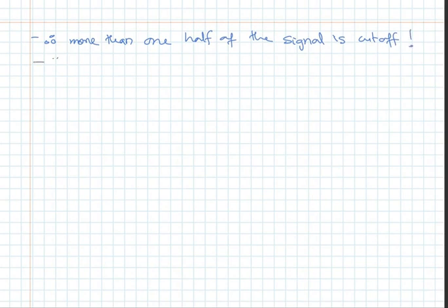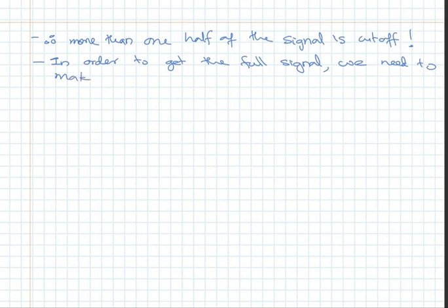In order to get the full signal, we need to make sure this input never goes below V gamma, no, 0.7.